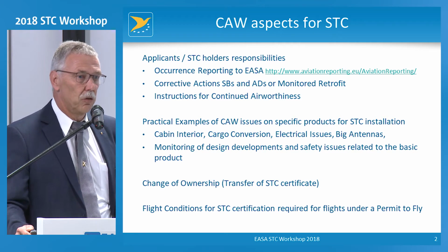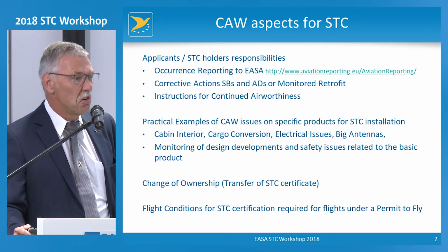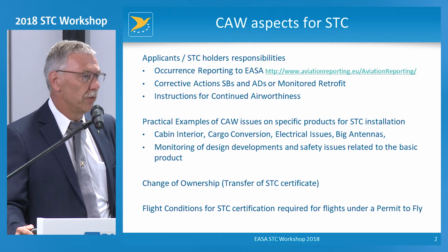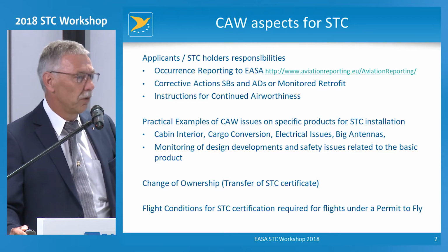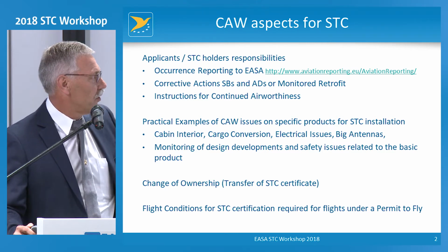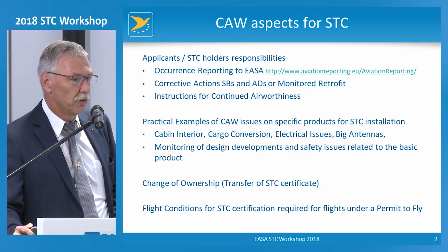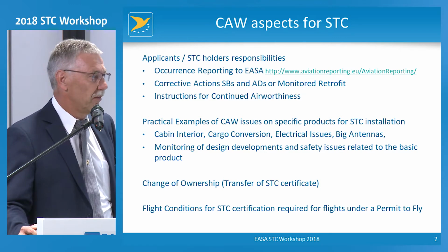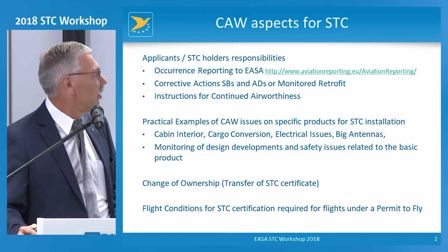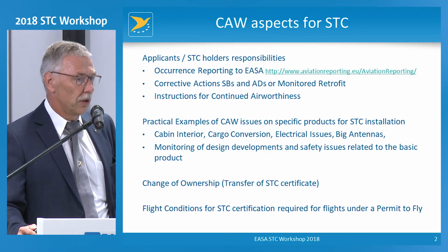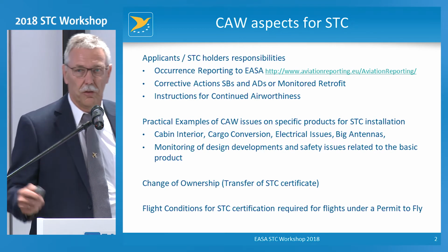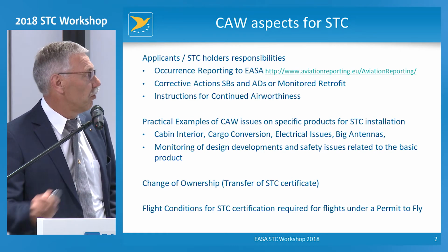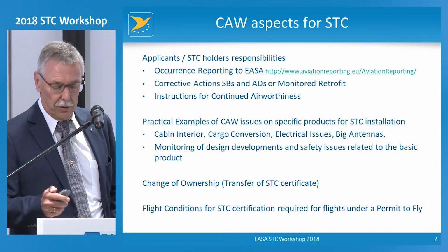If there's a need to change ownership of an STC, for instance, imagine Air Berlin went bankrupt, they had a DOA, they had STCs, and those aircraft need to continue to be operated, so you have to find out what to do. And this is just a list of what you can do if the change of ownership or STC holder has to be made. And then flight conditions for STCs, if you do flight testing, most of you will be aware of that. I will just mention some items that I believe are important.